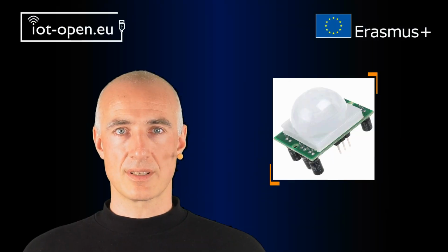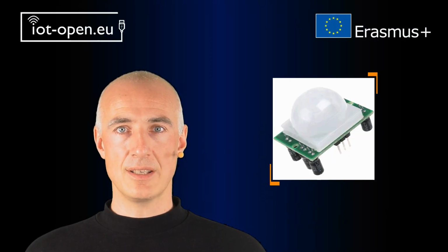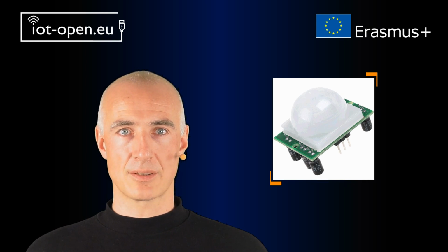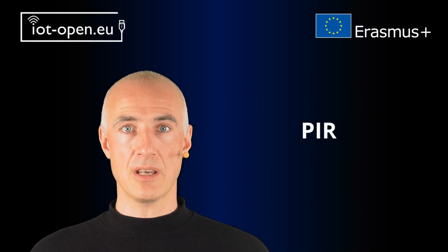The motion detector is a sensor that detects moving objects, usually people. Motion detectors use different technologies like passive infrared sensors, microwaves, Doppler effect, video cameras, and the previously mentioned ultrasonic and IR sensors. Passive infrared sensors are the simplest motion detectors that sense people by detecting infrared radiation that is emitted through their skin. When motion is detected, the output of a motion sensor is a digital high or low signal. The short name for this kind of sensor is PIR.